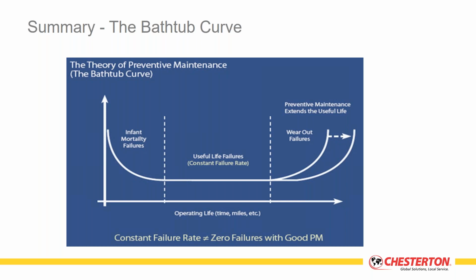It could happen that there is a quality issue of the component they install in the turbine. Or there is a possibility that they make mistakes during the installation, and for example, they damage the seals. So this is one area where we can help our customers to reduce the probability or the risk of failure, because with the split interlock seal, with the real mechanical split seal, we can help to make the installation easy and to avoid any kind of mistake during the installation.